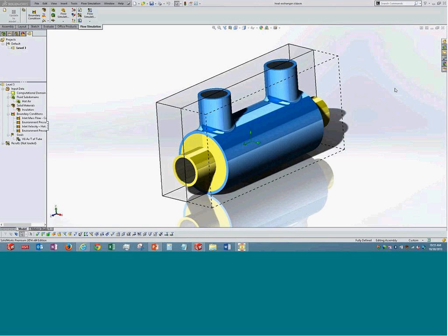If it is an external flow analysis, we can do it and permit certain leaks to be present in the wall, and we can visualize the actual leak that is happening at a certain location. Or the other way around, I would suggest having a closed domain itself. The location could be a bushing, or somewhere where you want to see if the forces are high enough to dislocate the bushing so that the flow can happen. Then we definitely use it and simulate the leakage through this particular bushing.